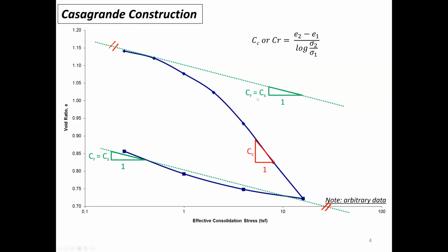The other thing we do in the lab is, since this goes beyond the maximum past pressure, you have to erase the disturbance that the soil has. And once you pass the maximum past pressure in the lab, you're creating a new fabric structure without any disturbance, because you're right on the spot in the oedometer, having the new soil structure.